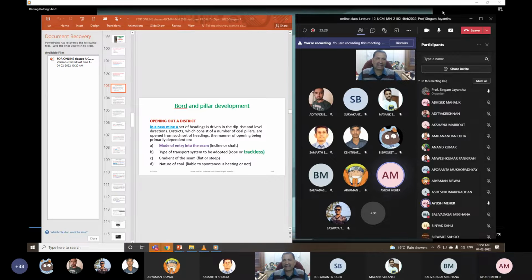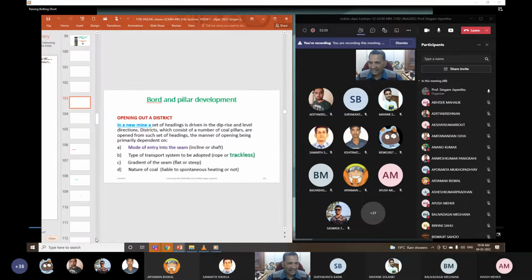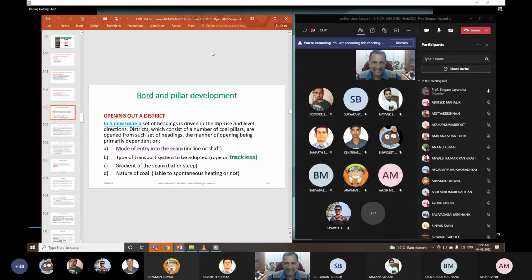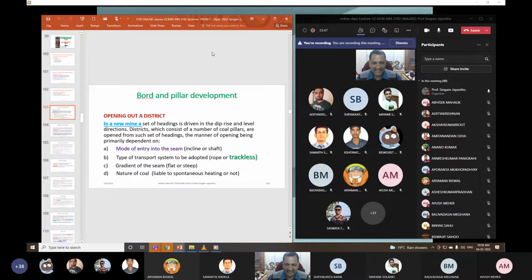Instantaneous detonator. Yes, sir. Now, generally, when we are working, there is already some free face, right? If that free face is sufficient, then there is no need for any delay detonator. Delay detonators are required to prepare the free face for the subsequent row or round.